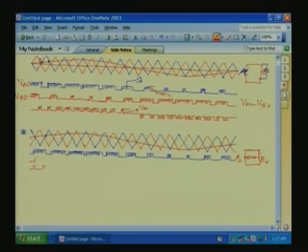Sorry, this is the one. So, we are comparing the red triangle with the modulating sine wave. Here, whenever the sine is greater than the triangle, the bottom switch is on. When the sine is less than the triangle, the top switch is on. The switching logic is interchanged, same as before. Only the triangles for the similar legs of the second converter are 90-degree phase shifted with respect to the same leg of the top converter, or converter 1.